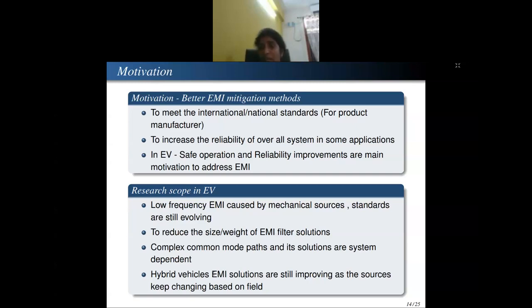What I mean by parasitic inductances is that you are connecting the converter in some form, and between each element there is a wire connected. If you use a solid wire, the inductance would be different. If you use some metallic platform with a surface area or a different method, the parasitic inductances can be reduced. So you can try to lay out properly so the parasitic inductance is less. In effect, this will reduce the parasitic capacitive currents.